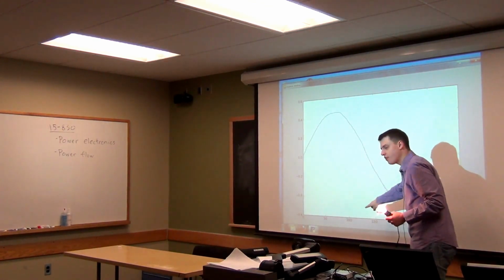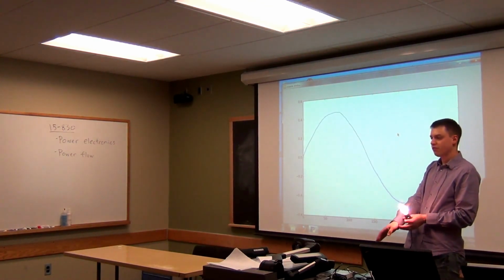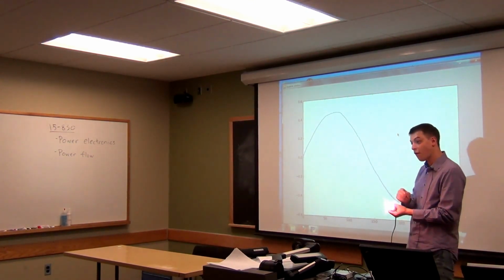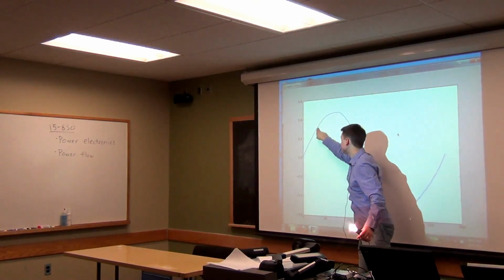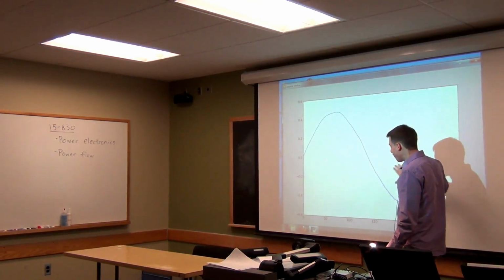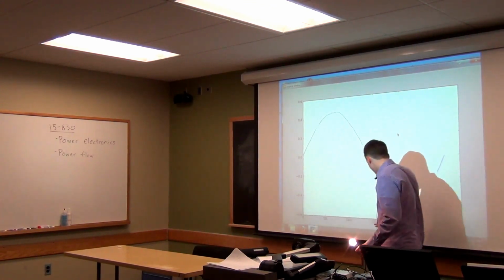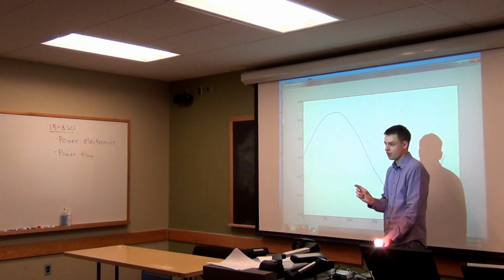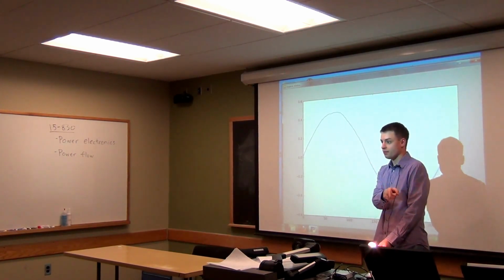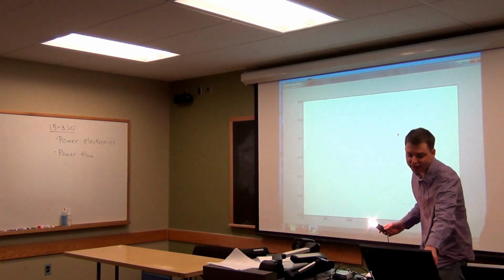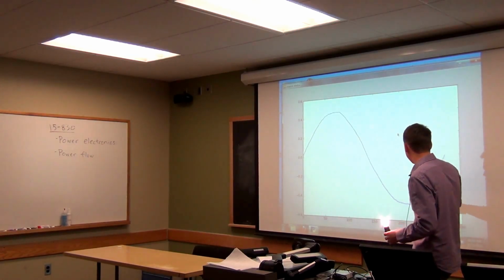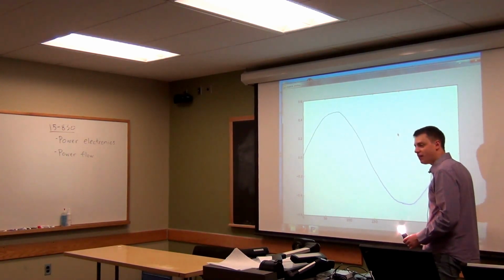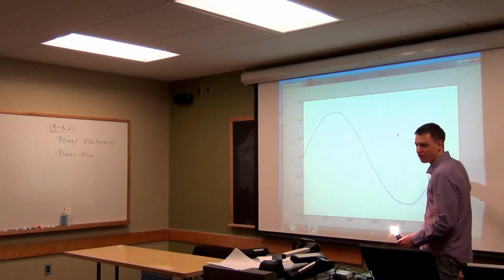The x-axis here is the number of samples, so don't worry about that too much. As I mentioned before, we are sampling little samples from this current waveform very, very frequently. Remember, this is happening 60 times a second. So I'm sampling this 100 or 250 times per 1/60th of a second, drawing that many samples from this A to D. And that lets me see what's happening in very, very high detail here. So this isn't actually that important. What it really should just be is one of these things here. This would be 1/60th of a second after one phase like this.